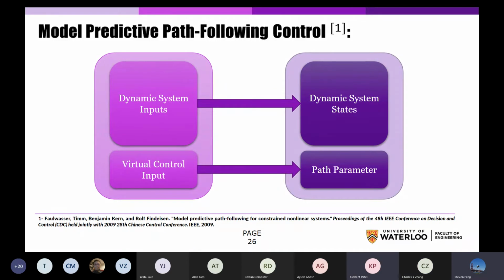Yeah, sure. The MPC output is the only desired output that we pass out, but that path parameter depicts how close you are to a destination, and when your reference line changes, that path parameter reverts back to 0 and goes towards 1. So it varies between 0 to 1 unless you reach your destination, the current pose and the goal pose.